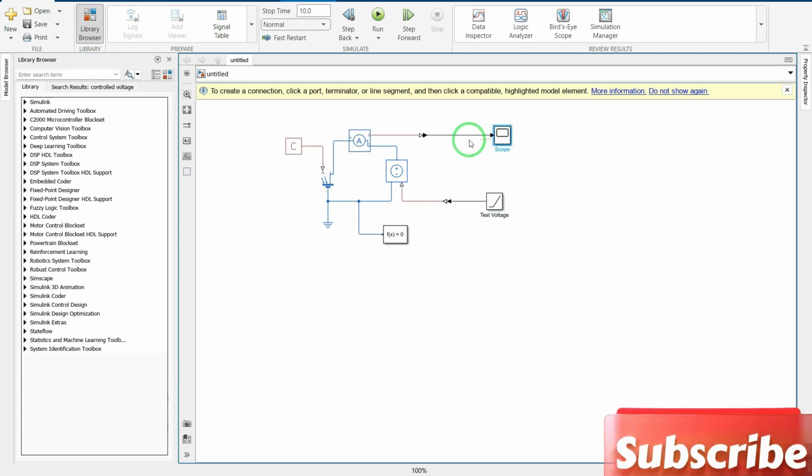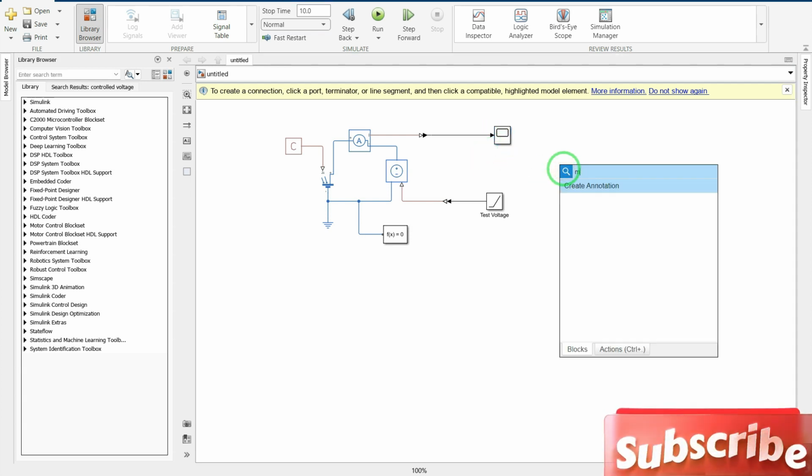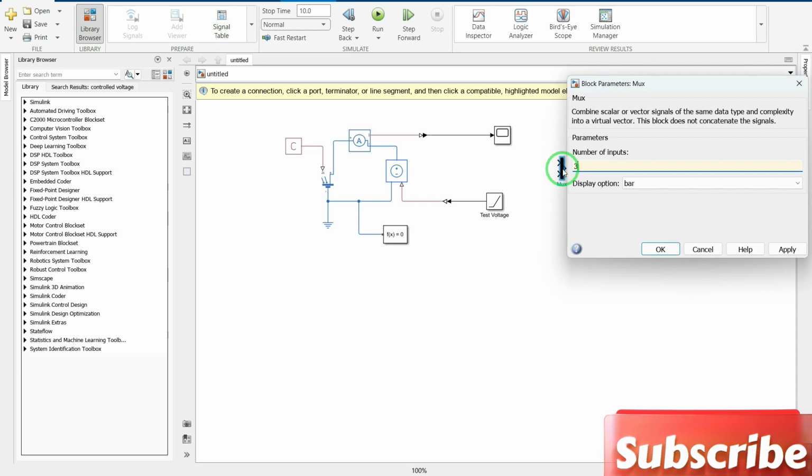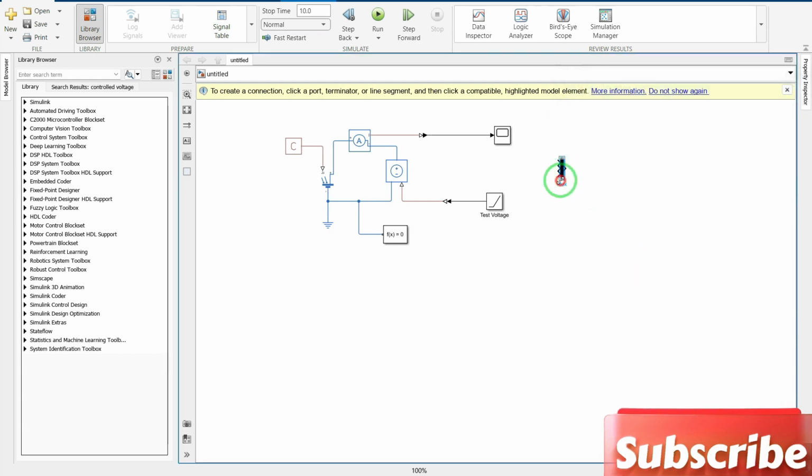At the end, we have our current plot here. Let's add a Max here. Increase it to 3 ports. Number of inputs, 3. Then we can designate the first one for the current, the second one for the voltage that we get from here, and the one in the middle can be the product of the current and voltage, which means power.